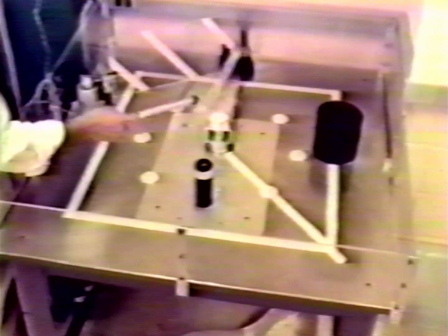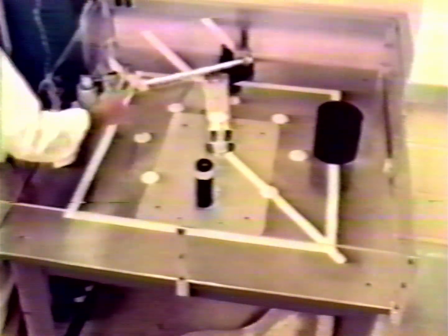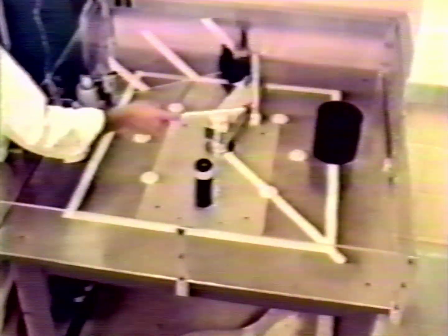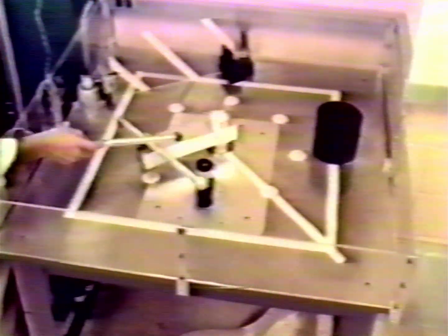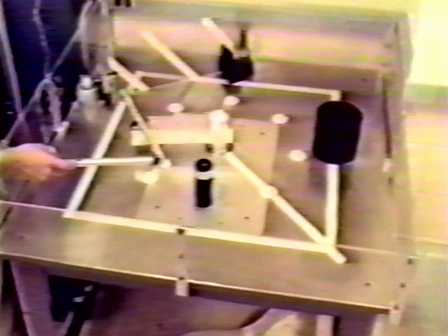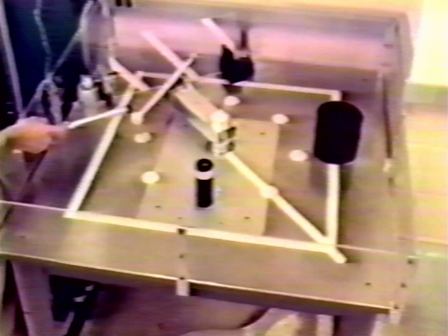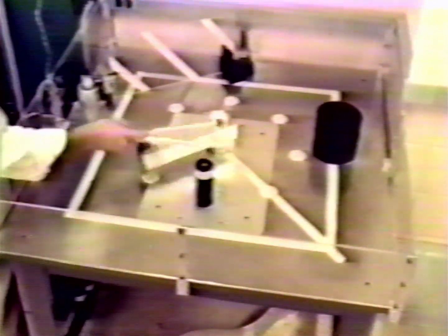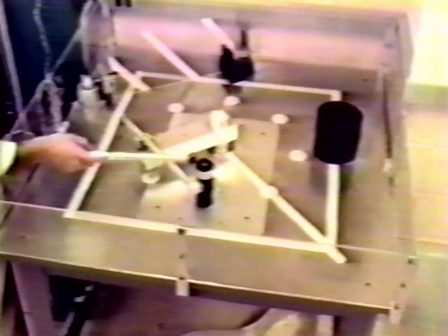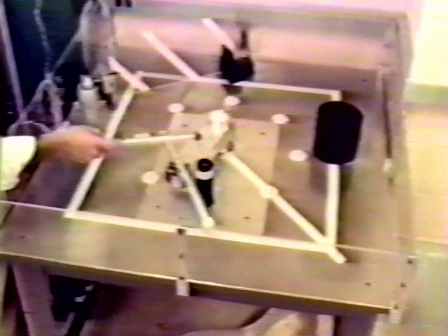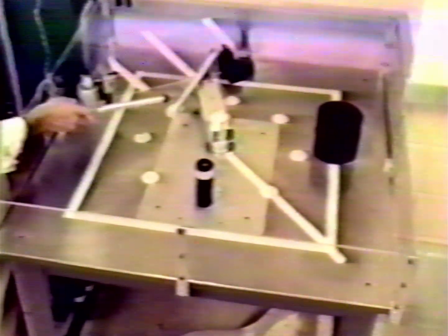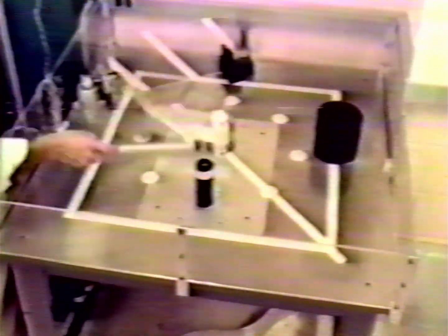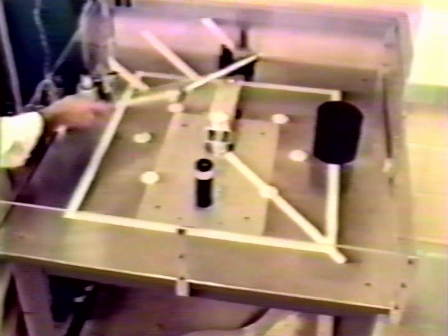This part of the tape is courtesy of Neville Hogan from MIT and Wyatt Newman from Philips Corporation. As you can see, this planar arm manipulator proceeds swiftly to the target position shown by the experimenter's wand. When any of the four black cylindrical obstacles are encountered on its way, the real-time motion planning during the collision avoidance phase is done using our algorithms. The information about the obstacles is provided by a TV camera installed in the ceiling.